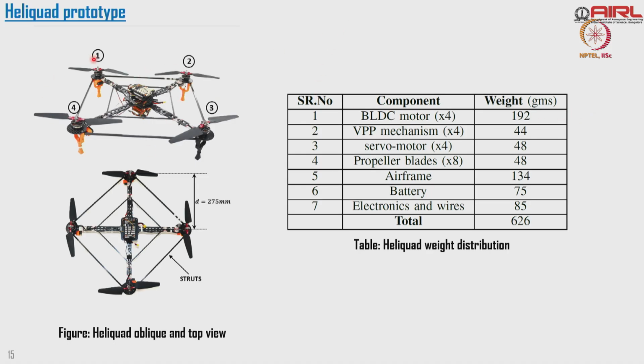So I decided to go ahead with the quadcopter. I am trying to give a typical box-like structure. Typically a quadcopter will have 4 arms alone, but we have provided additional bars because you have a variable pitch here. The variable pitch started producing vibration, so in order to minimize the vibration and reinforce the strength of the quadcopter, we have added 4 additional bars which provide necessary stability.